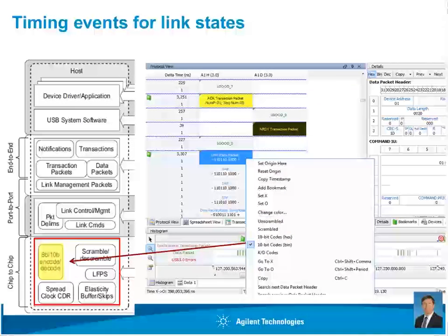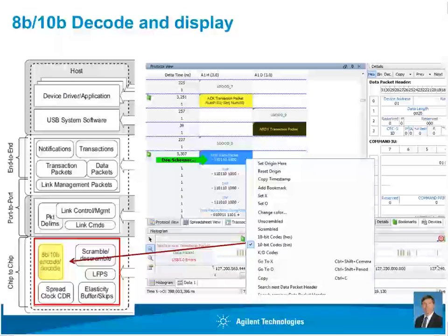While you're doing that, you also need to be able to check if any problem may lead you back to the low level of what were the 10-bit codes that were occurring across that link, and being able to display exactly here's the bit sequence that was sent across the link. Even if it is errored, being able to capture what happened here, or trigger on those events and look at repeating sequences, or trigger out to an oscilloscope or other types of devices to see exactly what's going on, trigger into your firmware tracing of what's happening there.